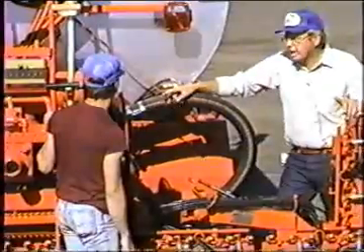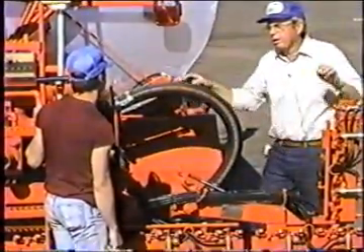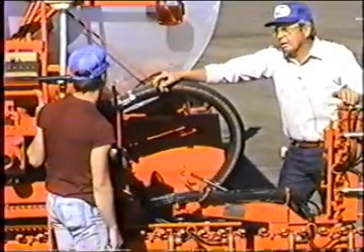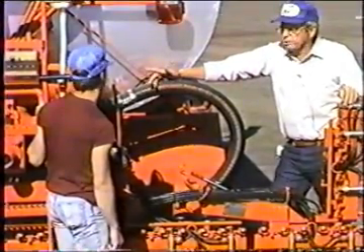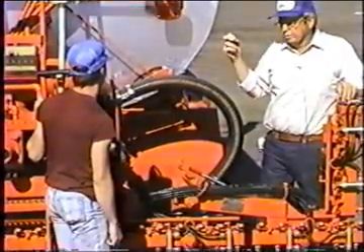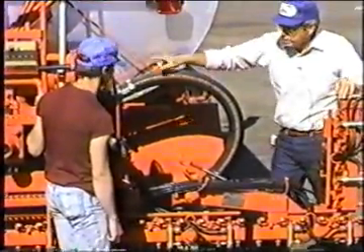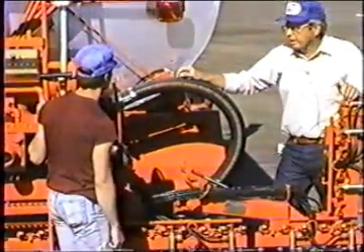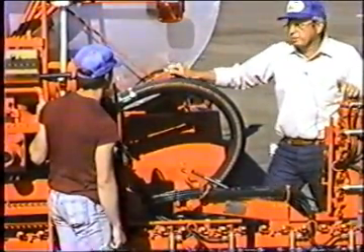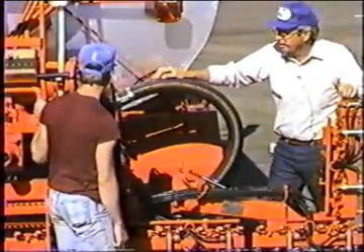Snug it up to where it quits dripping and reset the set screw. Okay, if you have to tighten it so tight that it won't swivel any longer before it quits leaking, it's time for a new O-ring. In that situation, you'd spin the nut off, take the O-ring out of the face, put a new O-ring in it, and put it back together and readjust it. It's got to be free to swivel. If it can't swivel, then I'm going to get to sell your boss a lot of these hoses, and these suckers aren't cheap.